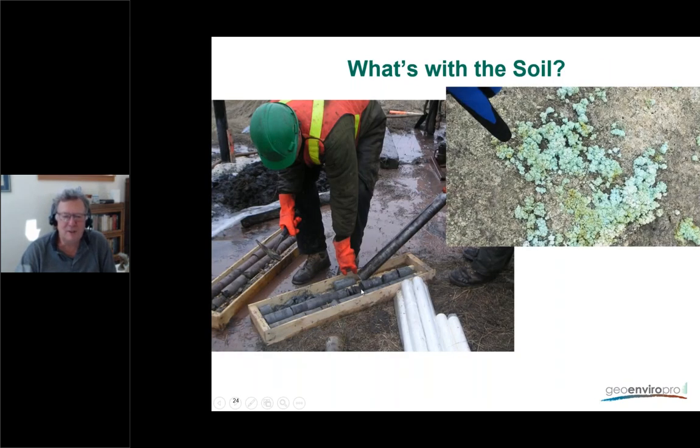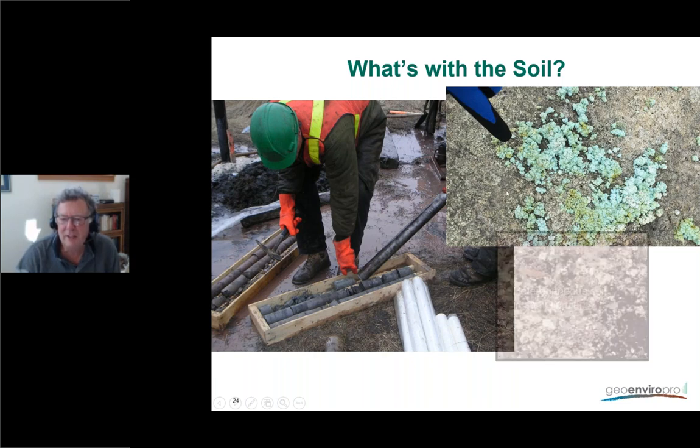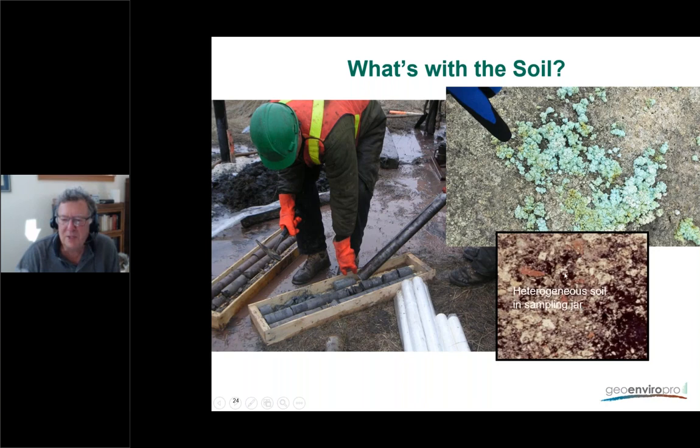Here we've got somebody that's logging some soil cores coming out of the ground. You'll notice there's a bit of heterogeneity in there, some fracturing. Here on the right side, this is a pile of silty material at a smelter site that was high in copper. We've got some malachite oxidation, or copper oxidation with malachite. And here's just a blown up sample of a sand, recognizing that when you look at our soil material, we know it's heterogeneous at small, medium, and large scales.